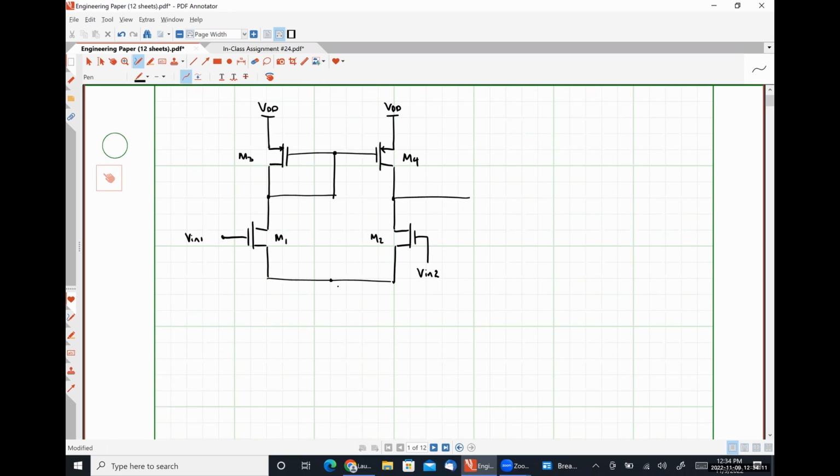And then down here, we have a tail current source. I'm drawing it this way, but we know that this is effectively a cascode current source that's connected to our bias network. So I'm just going to write 2 bias network out this direction, because everything here is independent of our bias network. Okay. So this is where we are at effectively in our design. Now we're going to move along to the next stage.